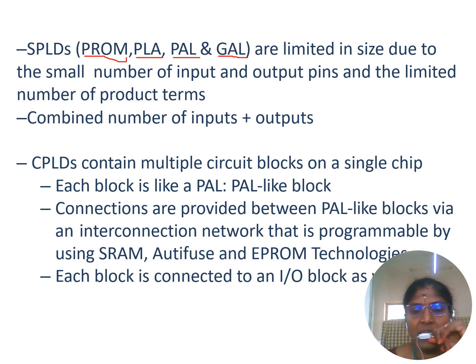So the SPLDs are limited in size due to the small number of input and output pins and the limited number of product terms. It has combined number of inputs and outputs. Due to this, the SPLD is not used for the large number of inputs, fan in and fan out. So we move on to the next one, complex programmable logic devices.